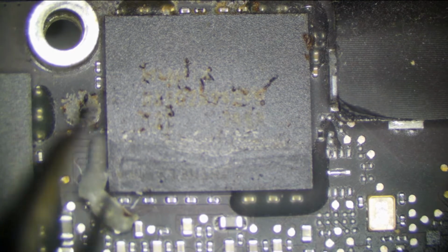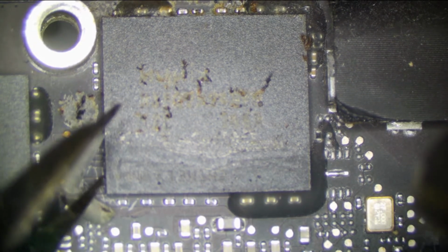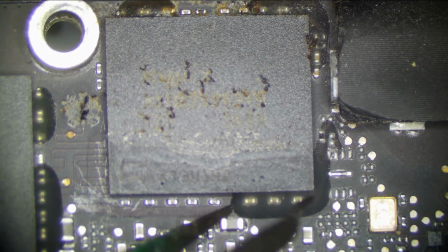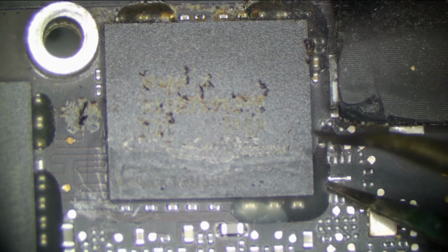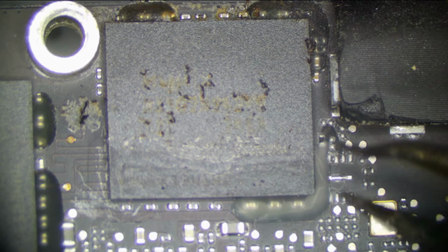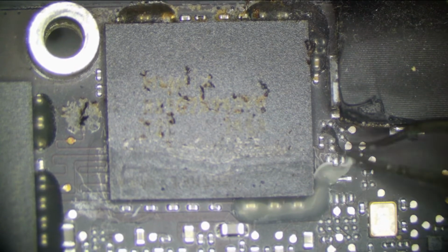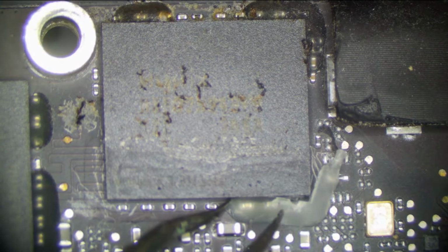A little more heat in there. Because then you'd have to reball it, and that's much more difficult. A little piece still under there. It's okay though. A lot of times you don't have to. I kind of don't like to heat these up fully because you risk killing them. So it may honestly be better just to heat from far away and not completely reflow it. Just get some flux under there to clear all the junk out from under it, and this edge bonding is being a real pain, so that is definitely what I'm going to do instead of a complete reflow. Because I don't really want to reball one of these. That would not be fun. That would probably make me cry.